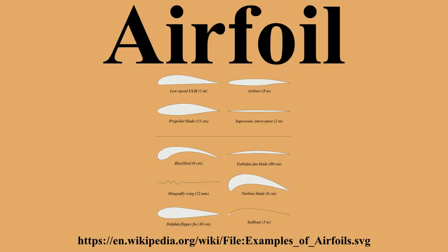angle of attack. This turning of the air in the vicinity of the airfoil creates curved streamlines, resulting in lower pressure on one side and higher pressure on the other. This pressure difference is accompanied by a velocity difference via Bernoulli's principle, so the resulting flow field about the airfoil has a higher average velocity on the upper surface than on the lower surface. The lift force can be related directly to the average top-bottom velocity difference without computing the pressure by using the concept of circulation and the Kutta-Joukowski theorem.